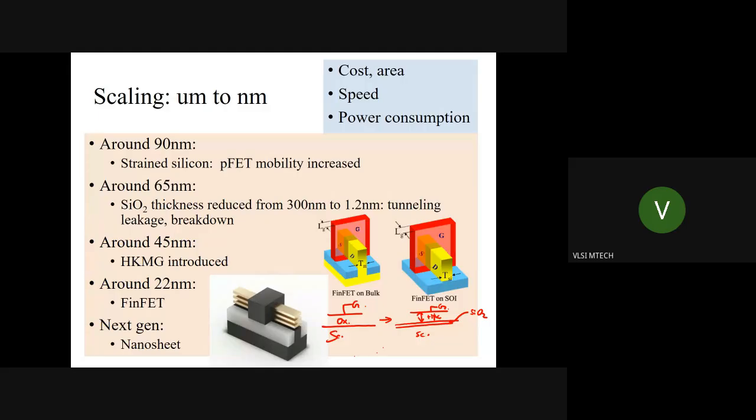What this does is, the high-K material, something like HfO2, has a very high permittivity, which is the K, the relative permittivity. I think it's of the order of 25 or so. I have to check, but it's of that order. So what that means is this material is very permeable to electric fields.